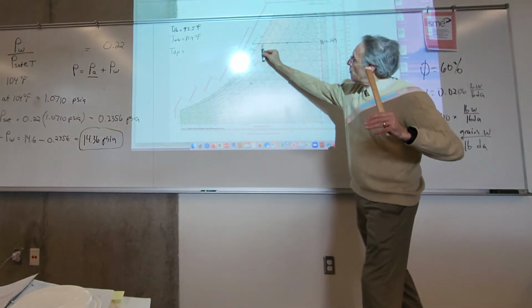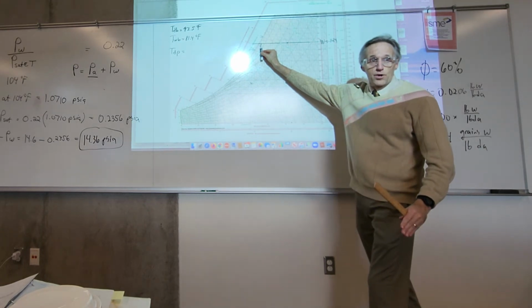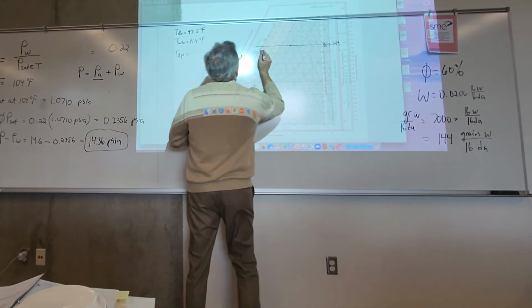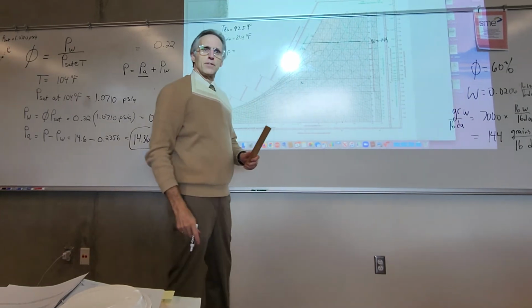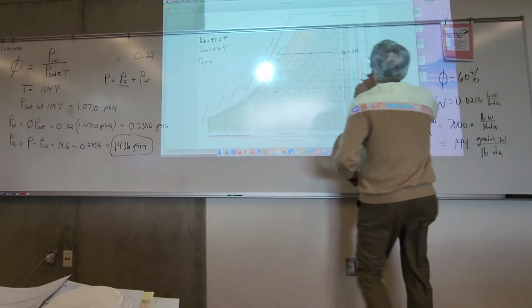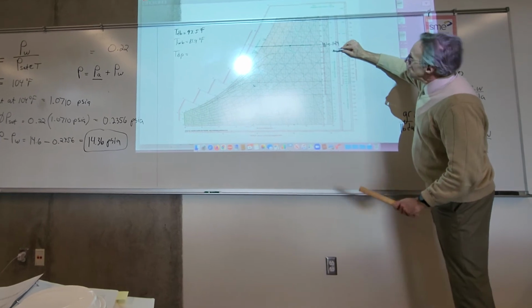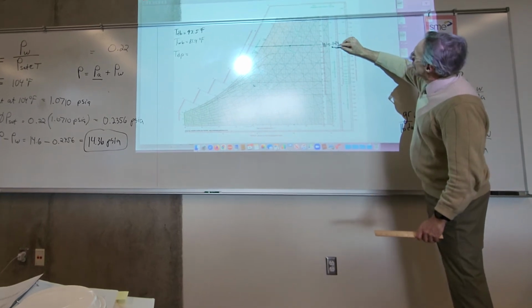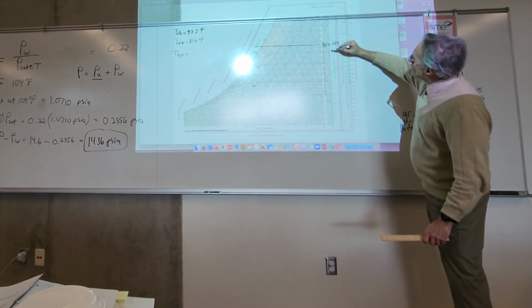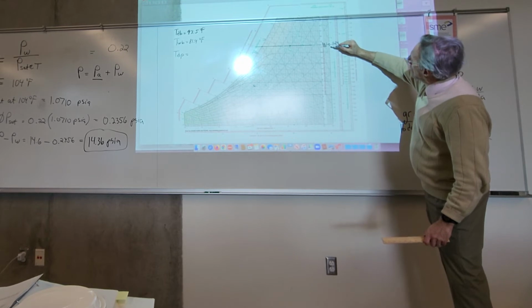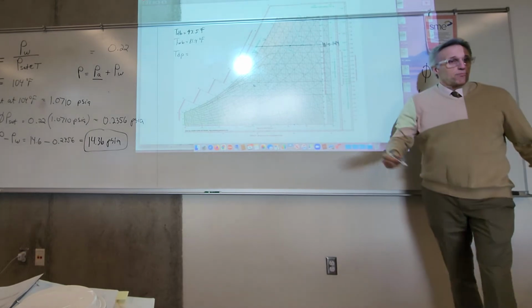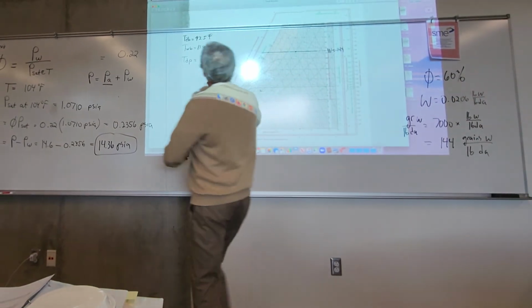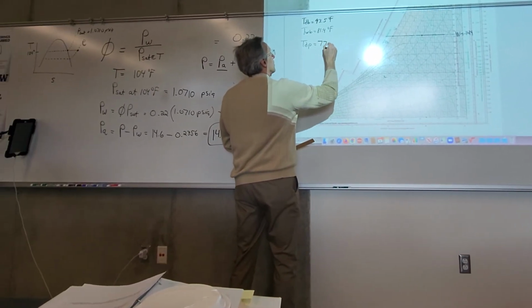As soon as we hit that, we start to condense water out of the air, and it looks like that is about 76, 77, 77 and a half. And if I read over here, it's easier on this side, 75, 76, 77, 78, so that's 77, so it's about 77.5 exactly.